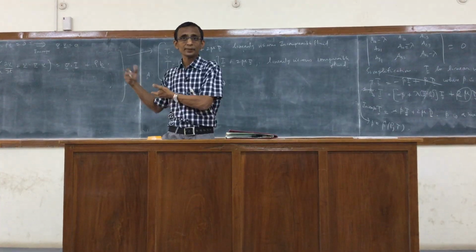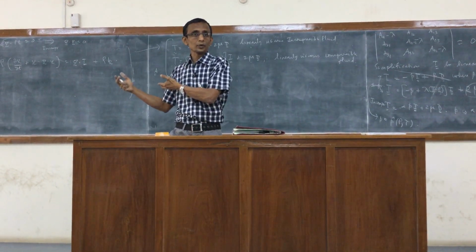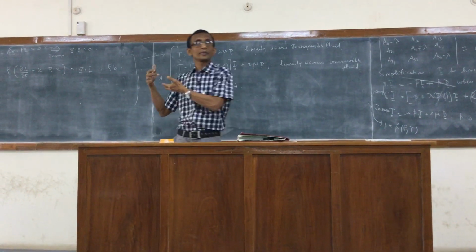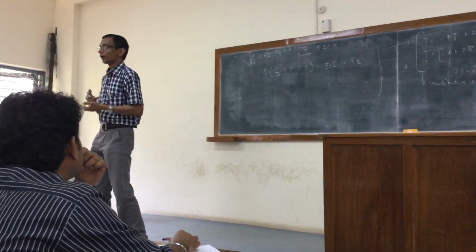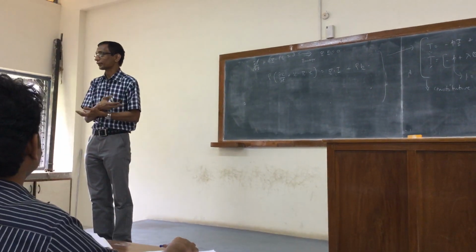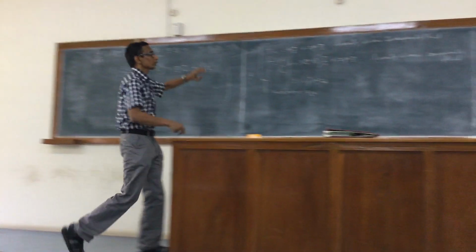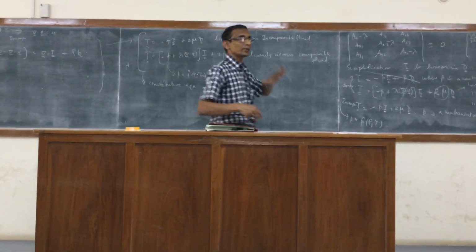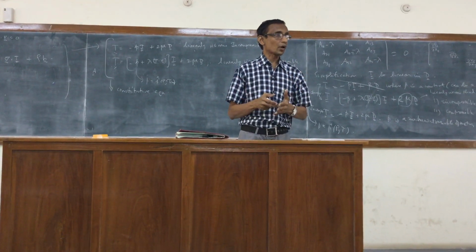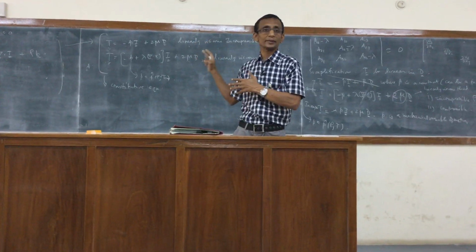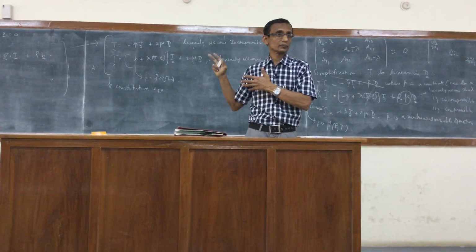The three hypotheses that we have listed, right, that the stress has to depend on the deformation tensor, the invariance with respect to the transformation of coordinates, and the reduction to the hydrostatic stress. These are the principles that Stokes formulated so that you have a general theory of constitutive equations, within the context of which you can look at special cases and particular types of fluids.